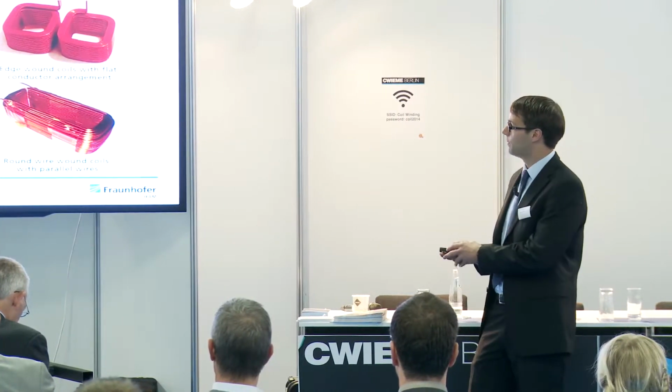First of all, what is the motivation to develop a casting process for coils? We all know the requirements on winding of electrical machines. We want to have high slot filling factor, whereas at the same time, we want to have a low thermal resistance to the lamination stack. We want to have minimized current displacement effects, of course, to minimize eddy current effects and additional losses at higher frequencies. And of course, we would like to have an automated manufacturing capability to reduce costs of electric machines.